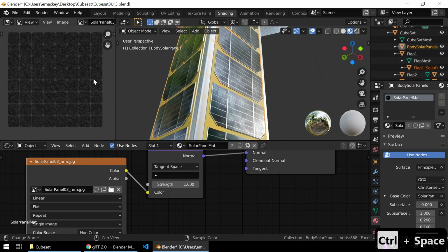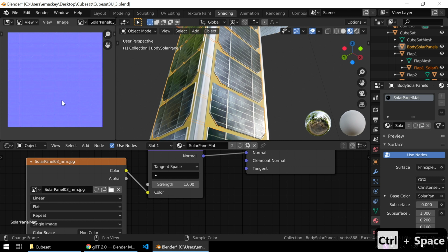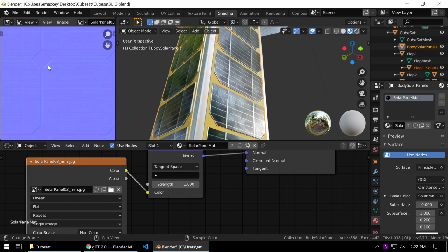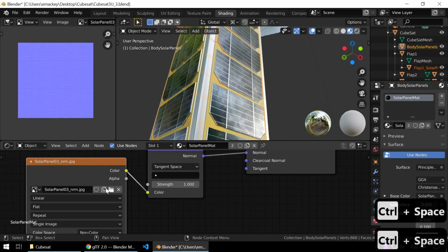This purpley image, by the way, is called a tangent space normal map. And it's this weird collection of purples and blues. And what you're looking at is actually not color there at all. It's vectors, X, Y, and Z, mathematical vectors. Encoded into pixels. Encoded, yes. So it's a whole set of axes per pixel. And it's describing the slope of the surface underneath.